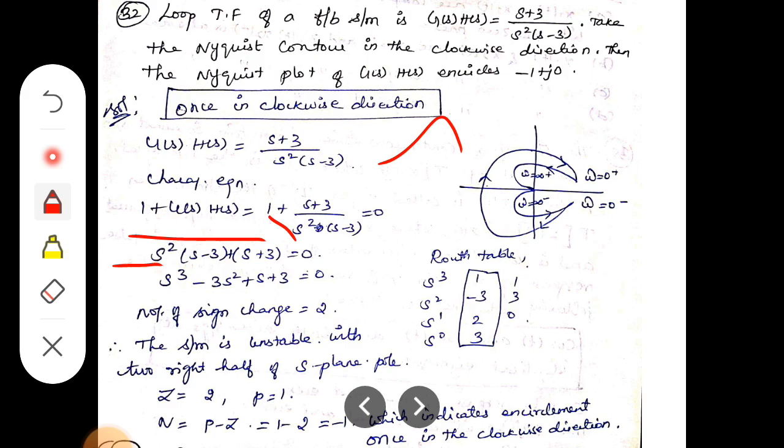For this, we move to the Routh-Hurwitz criterion. For the Routh-Hurwitz criterion, take the highest power in the given polynomial. So s cube is the maximum, so order 3. 3 is an odd number. So we write first s3, then s2, s1, s0 like that. So the first row is taken as the coefficients of s3 and s1, that is the odd powers. Those coefficients will be rewritten. In case s power 1 is not available, it is written as 0.